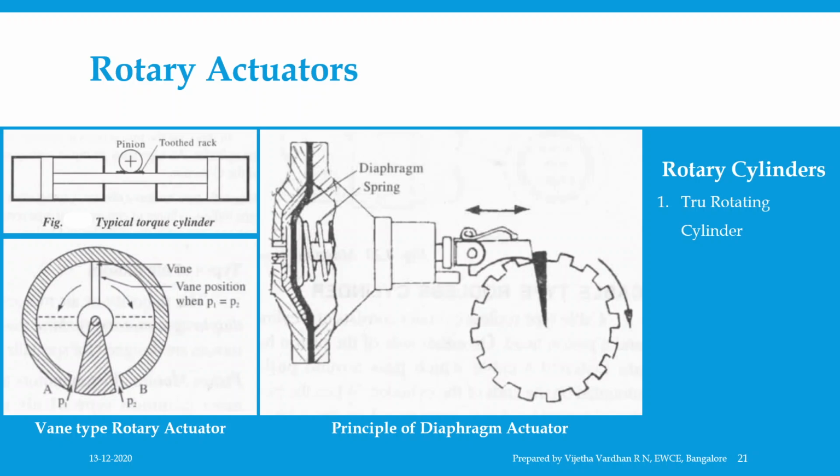The complete cylinder is mounted on a distribution gland which allows the cylinder to rotate relative to a workpiece. The other type is the rotating piston cylinder, one where the design provides for the piston to rotate freely relative to the cylinder with no loss of working characteristics. This requires that the piston seal be capable of accommodating rotary as well as sliding motions.